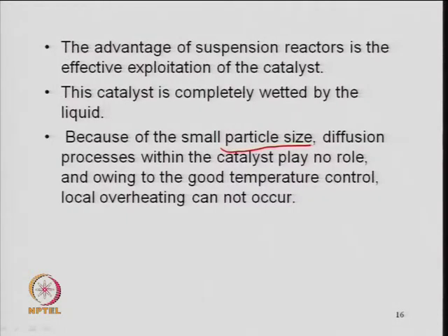And the complete catalyst is being used here, because it is a fine, low concentration of the catalyst in a large volume of the liquid. So, well dispersed fine powder or particles of the catalyst are well dispersed in the liquid. So, the gas will have enough time to contact with these catalyst particles. That is another advantage compared to a packed bed reactor, where most of the particle surface of the catalyst may not be utilized properly, right.